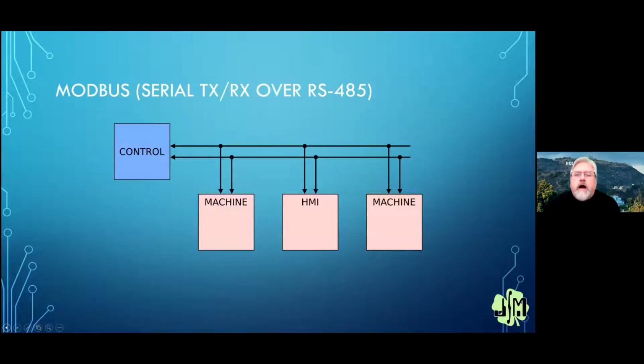Okay. Just to show you that protocols are the only thing that changes here. This wiring diagram looks suspiciously like the DMX wiring diagram, except you'll see I have arrows going back. And MODBUS is another protocol that runs over RS-485 wiring. That's a very, very simple serial protocol.